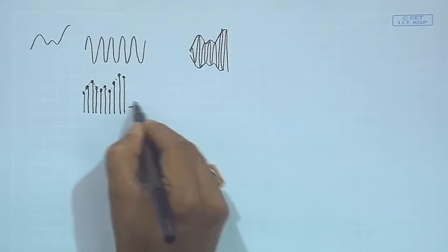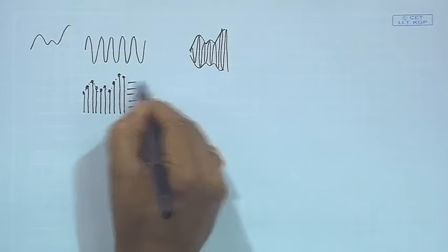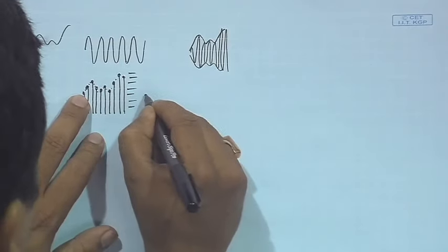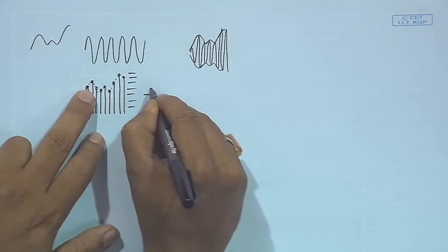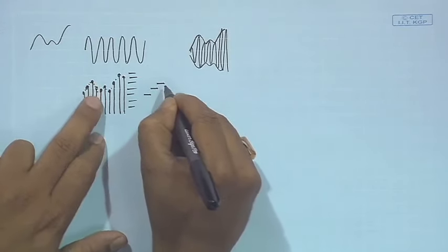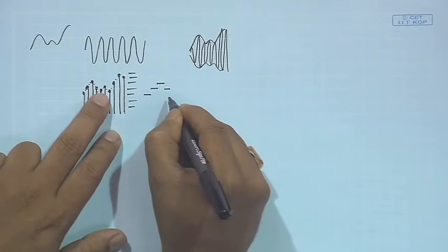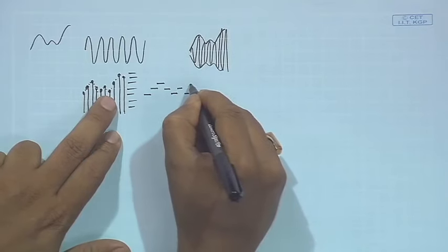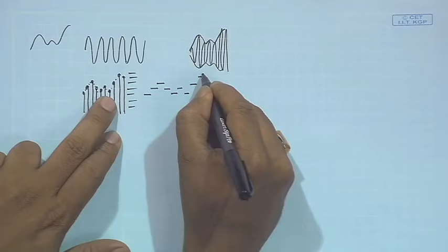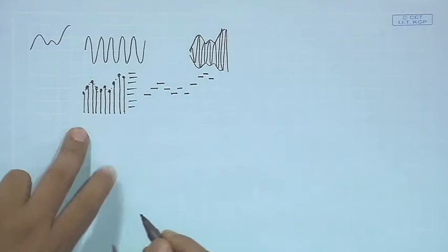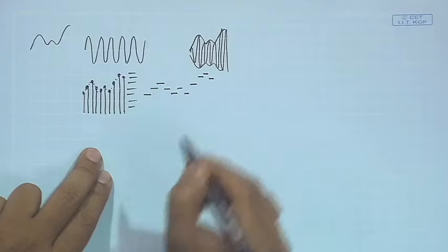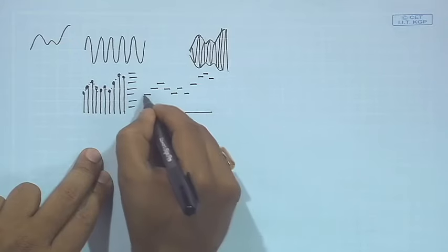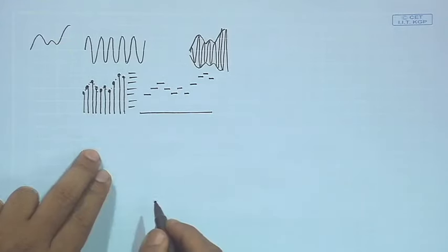So, if we have certain definite levels, we could imagine as if you are at this level, then you are at a level here, then you are at a level here, then again back there, back somewhere there, again there, again there. Something like this. So, quantization means that instead of having continuum amplitudes, you are now having discrete amplitude levels, right.